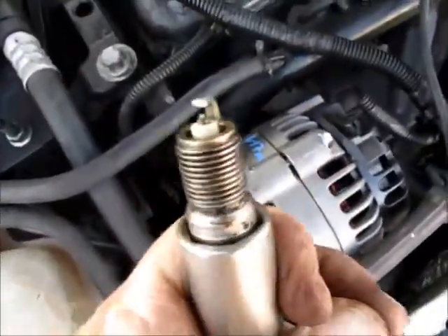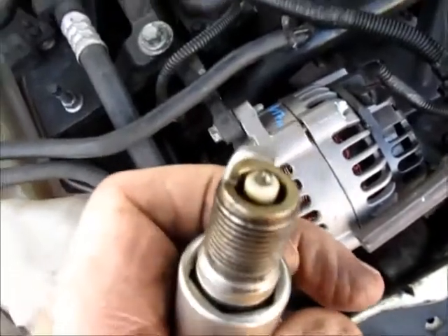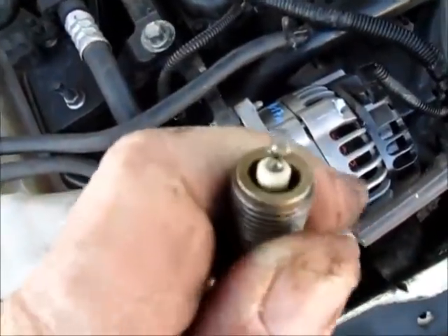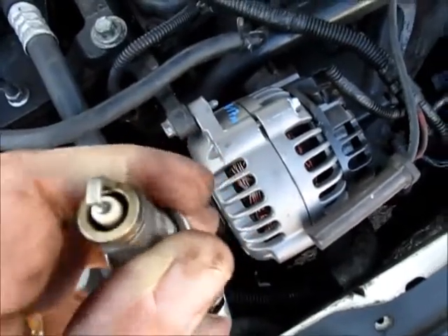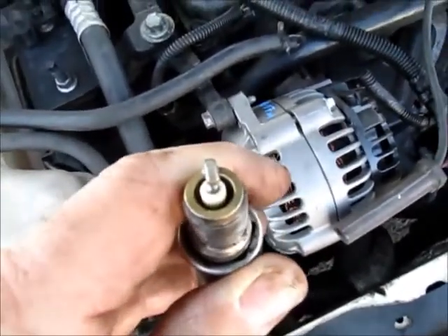So here's our spark plug, and it looks like I'm not getting any fuel really on it at all, but that could also be indicative of low compression. So you need 3 things for the engine to run. You need spark, fuel, and compression. And if you don't get air in the engine for some reason, like if you got a blocked exhaust or something like that, you won't get compression. If the valve timing is off, you won't get enough compression either. But you need to have all 3 in order for each cylinder to operate evenly.